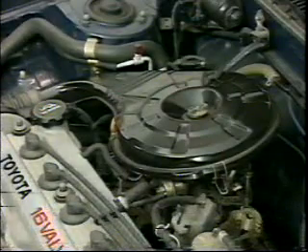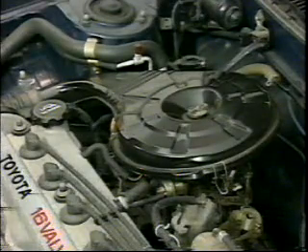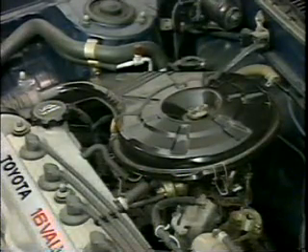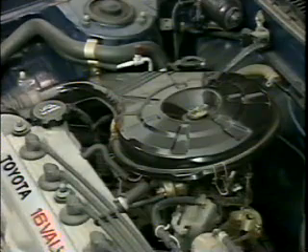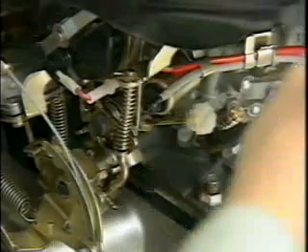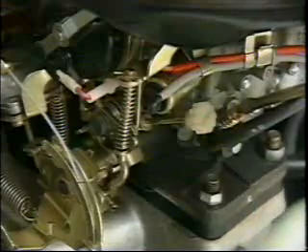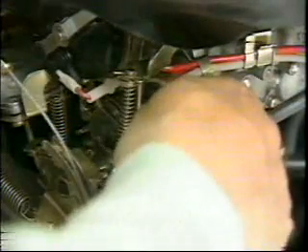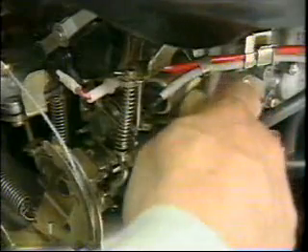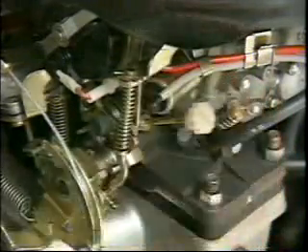Remember that the test must be done with the air cleaner in place. In some models with an air suction system, you remove the air suction vacuum hose and plug it with a hose plug. Turn the idle mixture adjusting screw to raise the engine RPM to its highest permissible idle setting. Then turn the idle speed adjusting screw to set the idle to the specified idle mixture speed.